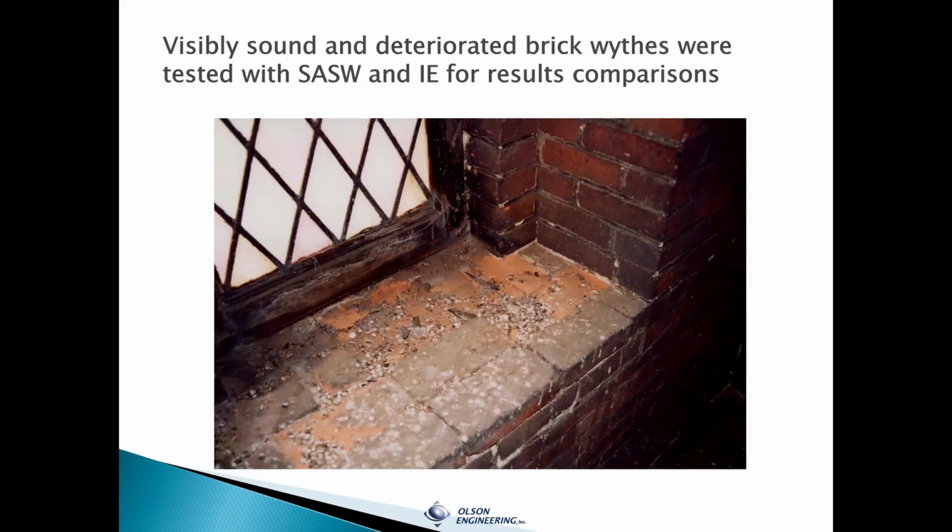So how did we calibrate this? We didn't have the advantage of any destructive testing on this project. It was relatively low budget. We had to calibrate it based on visibly sound conditions in openings of the windows and the doors versus really deteriorated conditions. So we could see how the data was in different areas, both in the impact echo and in the spectral analysis of surface waves, so-called SASW method. So that's how we calibrated.